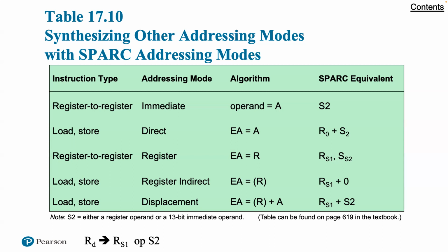The available arithmetic logic unit operations can be grouped as follows: integer addition with or without carry, integer subtraction with or without carry, bitwise Boolean operations for AND, OR, and exclusive OR and their negations, and shift left logical, right logical, or right arithmetic. All these instructions except for the shifts can optionally set the 4 condition codes: zero, negative, overflow, and carry.